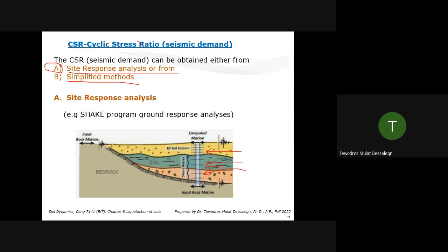So you can find it from the software, which means, in software, first you have to do your geophysical testing, lab testing, get the soil dynamic properties. And one input for Shake is what? The strain compatible properties of soil. Remember those degradation curves, G/Gmax curve and damping curve? They are direct input for site response analysis in Shake. That's how you represent the soil. They can be obtained from the lab or from field tests like geophysical testing.